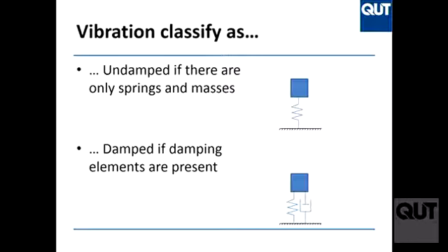That's not actually always true. Sometimes damping does some weird stuff if your vibration is forced, not free, and we'll see it next time. But very often, not very often is too much, say 70% of the times, especially with complex structures where vibration is not simply one mass and one spring, damping is so complicated that it's very difficult to model, and we simply neglect it. But if we can, we model it, because then it's more precise.